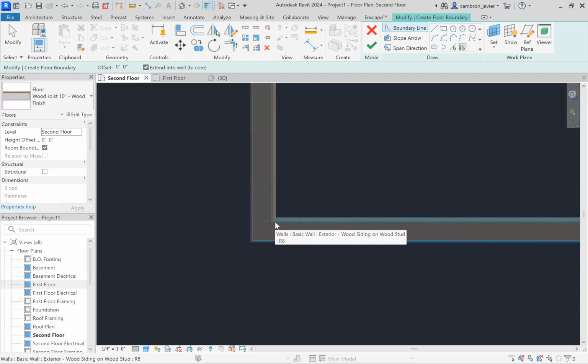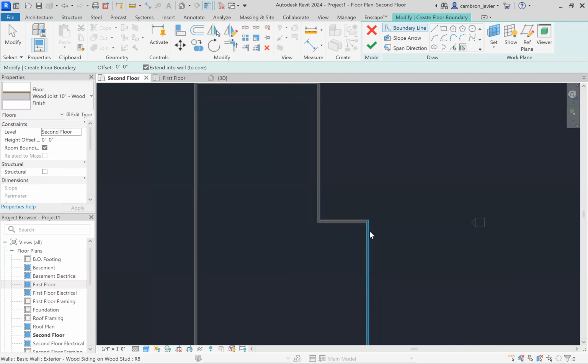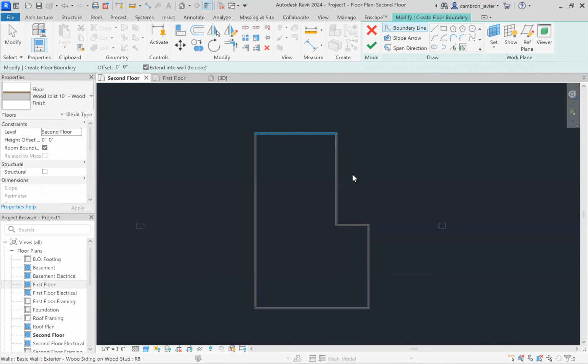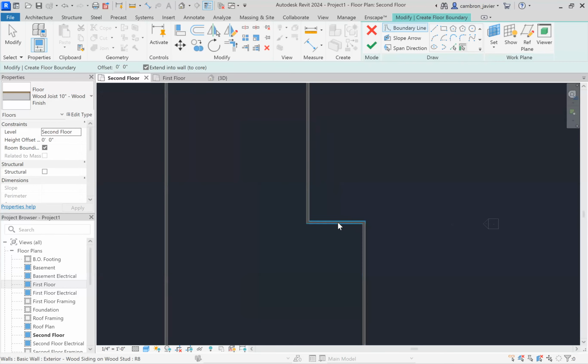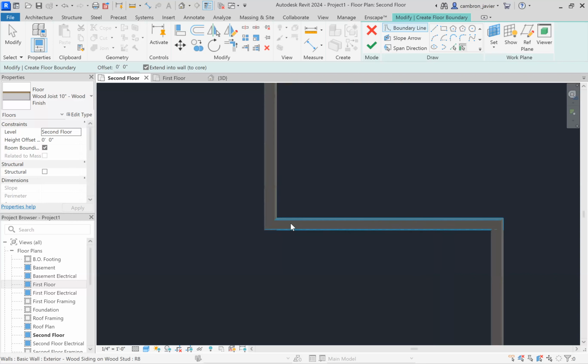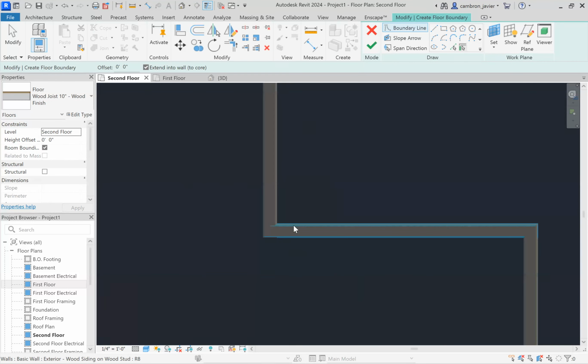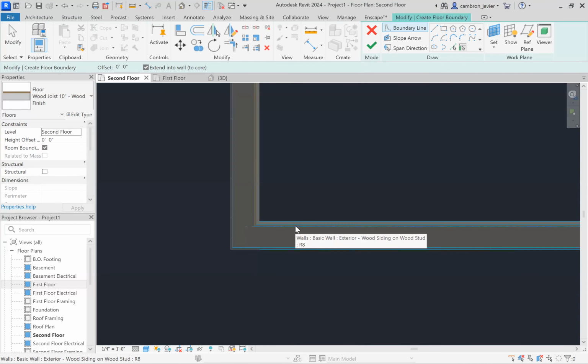And so that's going to tell Revit that it's the face of the floor. Now, with the pick walls, I can actually click and pick every single wall. But I also have this other really cool trick where we just hover over it, make sure the cursor is on the correct side. If you're too far away, you might accidentally click the wrong side. So zoom in, and then you're going to hit the Tab key on the keyboard. Okay, T-A-B, Tab. It's typically on the top left side of your keyboard.